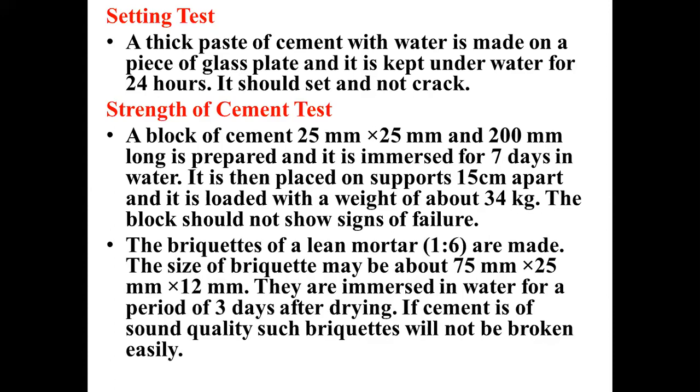Otherwise, we are going to prepare a briquette, which is also of irregular shape or size, of mortar in the ratio 1:6. The briquette may be about 75 mm by 25 mm by 12 mm. They are immersed in water for a period of 3 days. After drying, if the cement is of sound quality, such briquettes will not break easily. So that is the test for 3 days. It should not break easily.